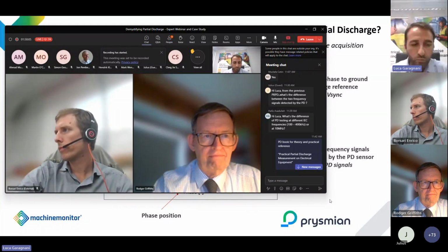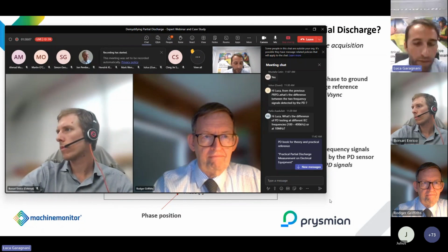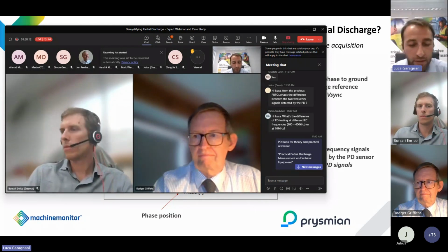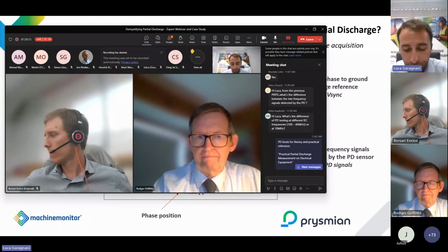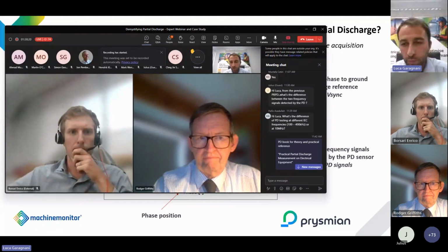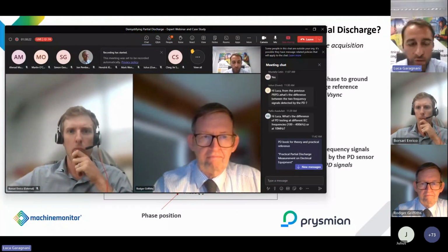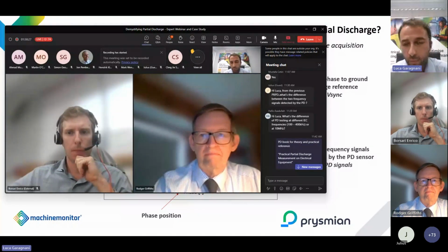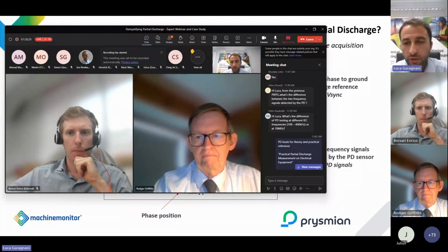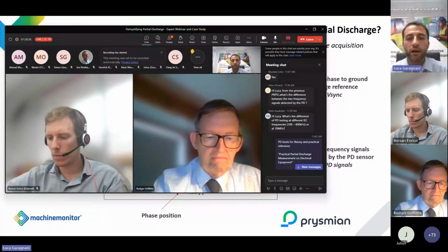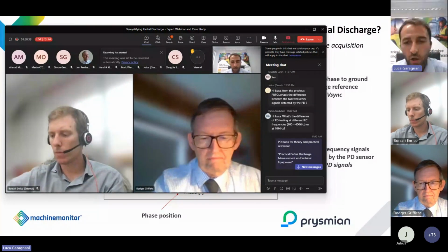All right, so this is a very good question, and it comes back to the discussion of millivolt and picocoulomb. And I know when we do field testing, this is a hot topic. Most of the instruments that you can find in the market also offer the possibility to measure in picocoulomb, and you need to be careful to utilize that functionality properly. When we talk about the picocoulomb measurement, we want to work in the IEC, and the IEC standard does not give you a specific frequency. It does not say you need to have 10 to 20 kilohertz. No, it gives you a frequency range.